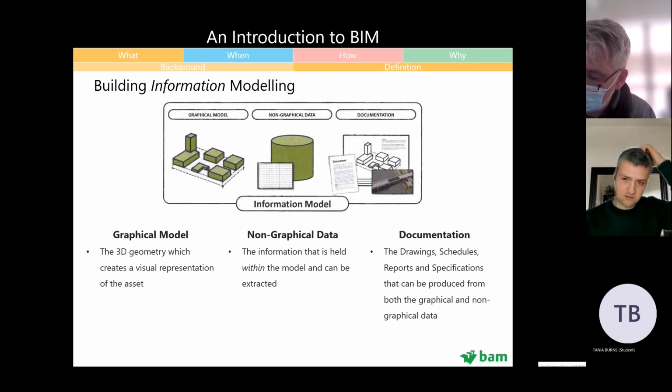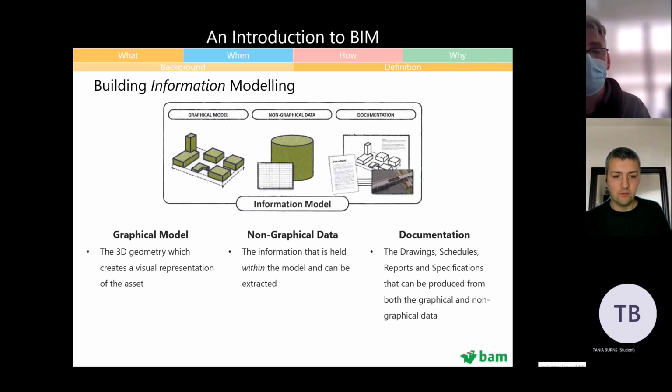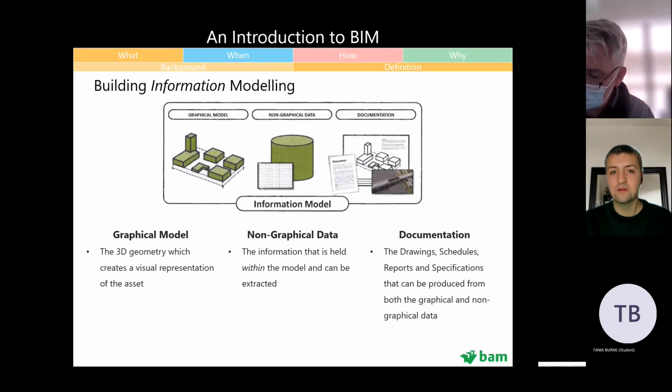That's probably hard for you to understand just from this slide alone, but as we model, we can set up the sheets, and if you just take, for example, a ground floor plan, that drawing updates as you model in 3D. So as you move the walls here and there, put doors in, windows, your drawings are just updating as you go, and they're ready for you to just hit the button, export, and your drawings are exported.